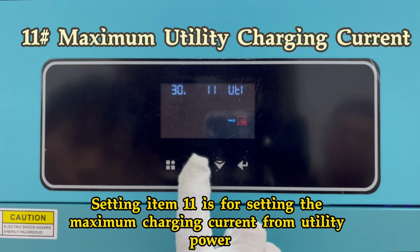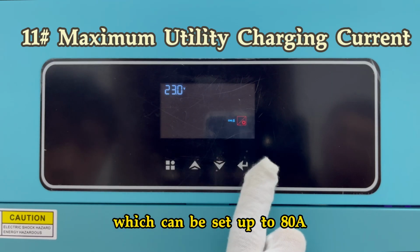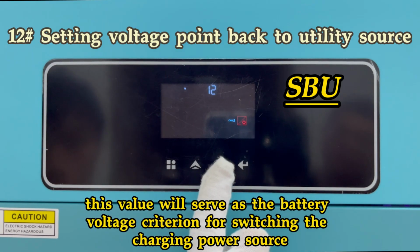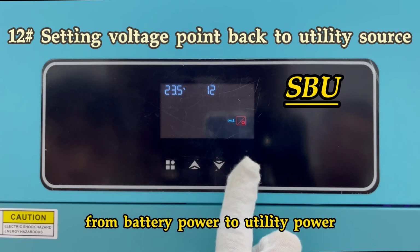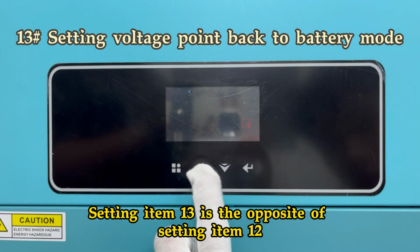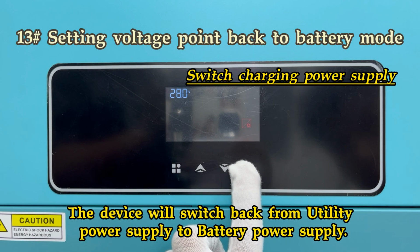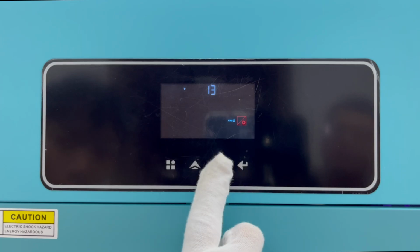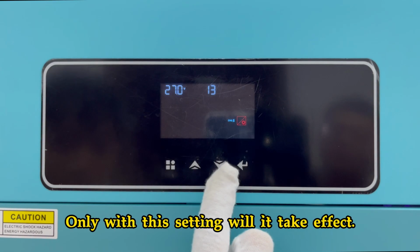Setting item 11 is for setting the maximum charging current from utility power, which can be set up to 80 amperes. When selecting SBU, this value will serve as the battery voltage criterion for switching the charging power source from battery power to utility power. Setting item 13 is the opposite of setting item 12. When the battery voltage rises to the value set here, the device will switch back from utility power supply to battery power supply. After setting options 12 and 13, disconnect the input voltage, then restart the utility power. Only with the setting will it take effect.